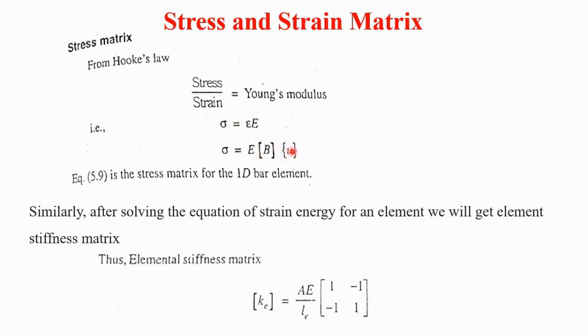So this is the stress matrix for the 1D bar element: sigma is equal to Young's modulus E into B into U.